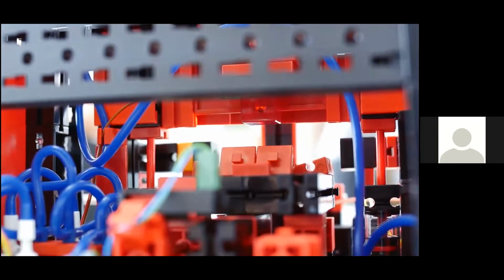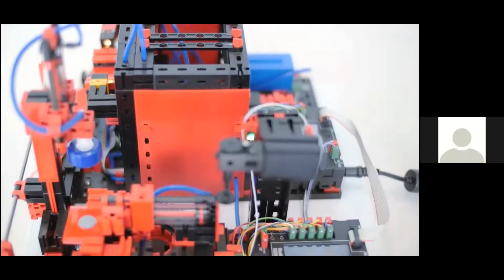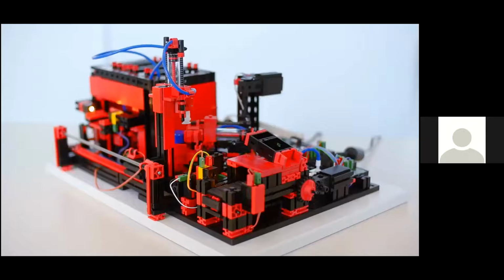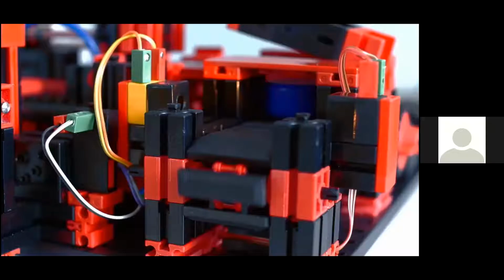choice, with once again, a relay board for motor polarity reversal, and both a multi-pin connector, 34 pins with a grid of 2.54 millimeters, as well as additional PCB terminals with push-in connections for all inputs and outputs. And again, the limited edition 9-volt version in this case will require 2 Robotics TXT controllers, so 2 120-volt power adapters will be required for all operation.